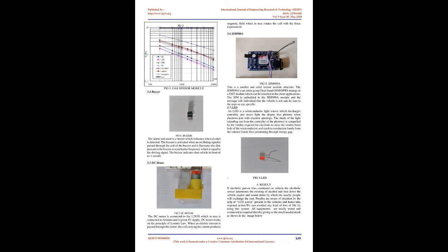3.2 MQ3 sensor. The MQ3 sensor is made of a tin dioxide, SnO2, sensitive layer. It is arranged in such a structure as to give high sensitivity to alcohol and low sensitivity to benzene. It has a simple drive circuit to give fast response, stability, and longer lifetime. It has a clear interface type. On the sensor, port pins 1, 2, and 3 represent the output, GND and VCC respectively. The specification of the sensor is described in the table below.